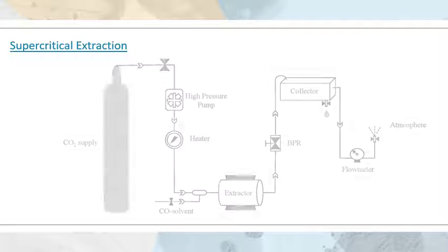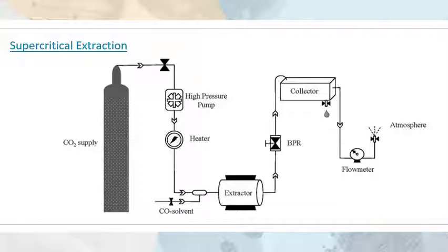Supercritical extraction. The supercritical extraction method has been developed in recent years. It is used to extract substances from a matrix using a solvent at supercritical conditions, where distinct liquid and gas phases do not coexist. Supercritical fluids can diffuse through solid matrices, similar to gas, and subsequently dissolve materials like normal liquids. Since many supercritical extractions are conducted close to the fluid's critical point, small changes in pressure or temperature result in large changes in the fluid's density. This unique property leads to density-dependent selectivity of the supercritical extraction.